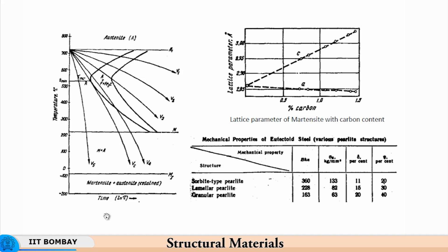So, there are steels with high manganese, where the chemical composition is such that martensite start is just below the room temperature. Now at room temperature, if you cold work the material, it is relatively soft, but as you work the material, because of the mechanical energy supplied to it, the martensite start comes above the room temperature.